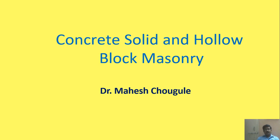When you are discussing strength, or when you expect more strength, in such cases you can use solid concrete blocks. But in the case of non load bearing walls, where you don't expect much strength, or you are expecting low weight, in such cases hollow block masonry is used.